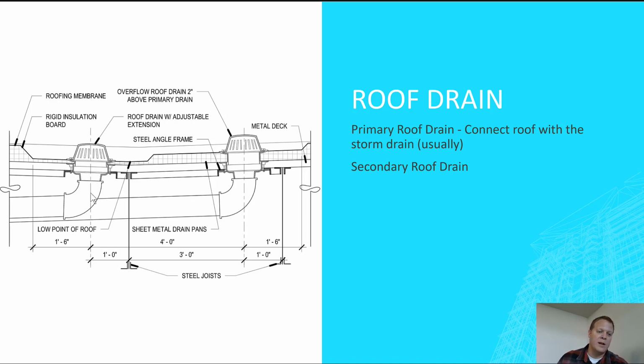So a lot of times folks will swap it, and they'll make the primary hooked up to this pipe over here. If the infrastructure is not ready for this, they'll hook up the primary to the secondary pipe. So if there's a rain event, the rain goes out of the building, but daylights outside the building, into where the secondary roof drain would normally go. And you just have to remember to swap these back. I've seen it before in warranty where we didn't do that.